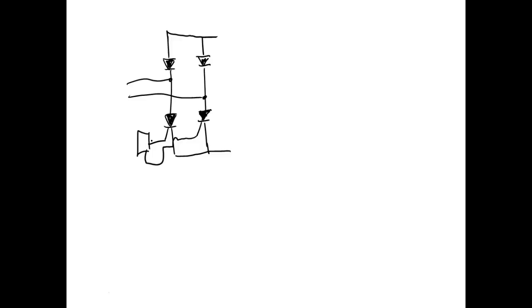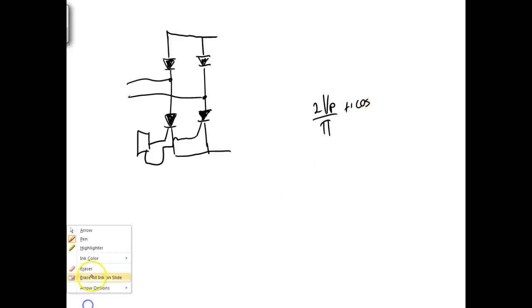Yeah, that's what it is. But see, the cosine of 90 is 1, so that's going to be 1 plus 1, which is 2 divided by 2, which is 1. And then we come up and get the same thing that we would get for half wave, and I know it's got to be less than that, right? So that's got to be the wrong formula. Yeah, so the formula that gives us 2 V peak over pi, which is for full wave, and then it says times 1 plus the cosine. So this is why I realized that formula couldn't be right.